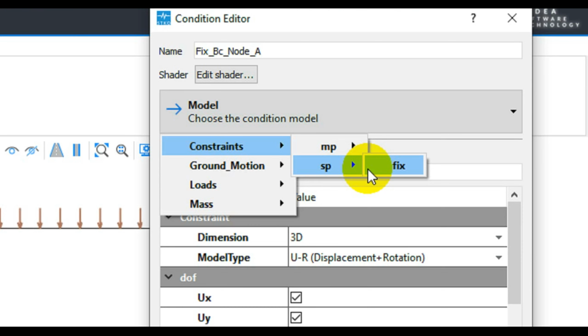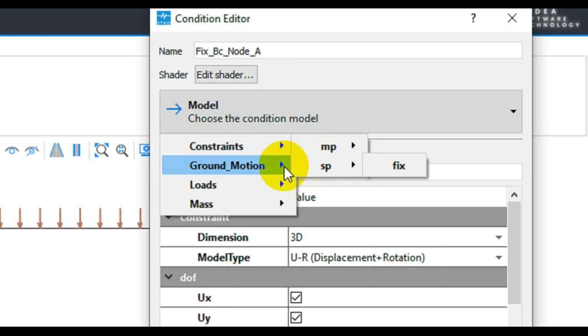And you will not even be able to select that point because in STKO environment you cannot do that. And if you want to assign a fixed boundary condition to a node and you are selecting another region, then it will not create any sensible results for you. If you want to consider ground motion data, for example, then you should select a choice that is making sense for you and your criteria other than just going to define it here.